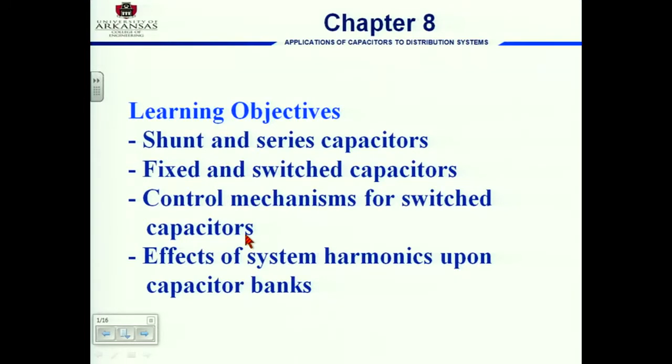But voltage, right? You have a voltage regulation, right? And you run the first case without shunt capacitors in today's homework. And then you wanted to improve the power factor at the substation, right? And then you put shunt capacitors. Well, you know that you don't have just one big switch capacitor. In today's homework, you run two cases, minimum load and maximum load.